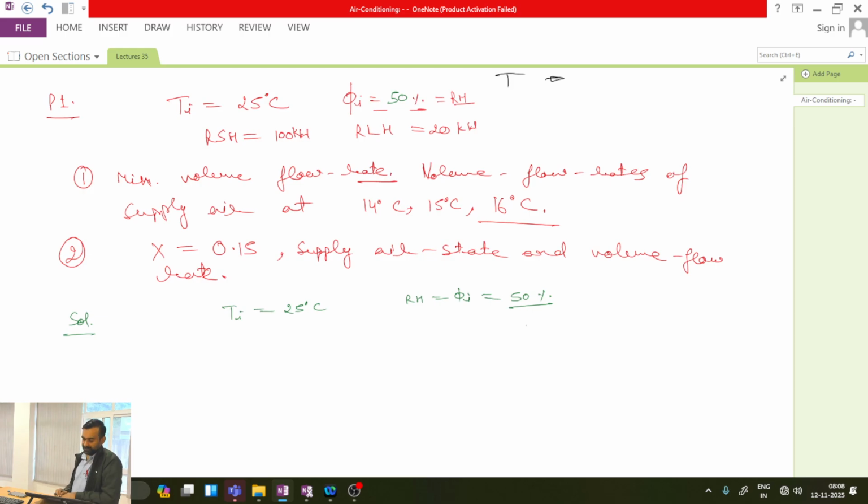So you are finding difficulty. Let's see. I'll show you first one method. Here we will try to do it without even plotting the processes on the psychrometric chart. Of course, for obtaining certain properties, we require the psychrometric chart, but let us attempt first to do it without that. So first, we have the indoor condition as 25 degrees Celsius and 50% RH.